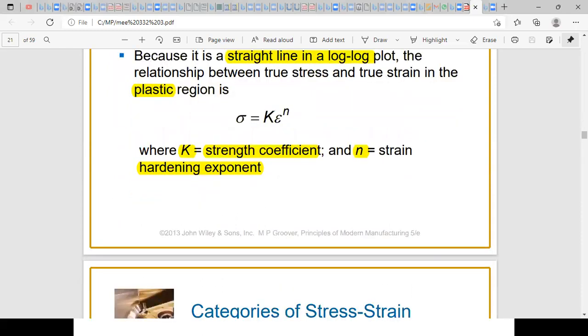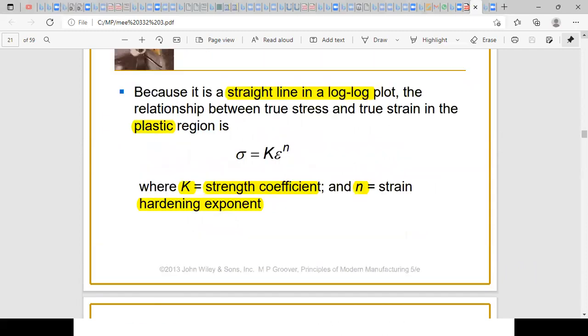Sir, I have a question. Why does the material become stronger when strain increases? Because, look, to continue deforming it, you still need to increase the stress. So higher stresses are needed to deform it, so this material is stronger, because it can sustain higher stresses. While when you start the necking zone, with lower stress values you can continue to deform.